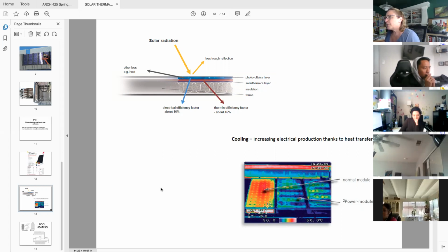Flat plate collectors get up to about 180 degrees, 190, and evacuated tubes can get well over 200. Also because with the heat pipe ones, they're working with the hot vapor, so they can get really, really hot, which is why they can be highly efficient in the cold climates, because you're generating more hot water at the extreme times of year.